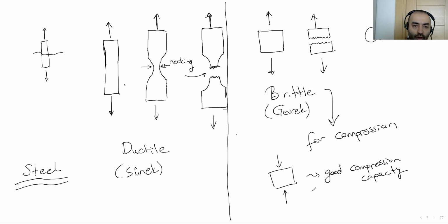It gets deformation, and we understand that, yes, it's gonna fail soon. Be careful. But brittle materials fracture suddenly. It doesn't give an alert. We don't know when it breaks. So that's why we don't use this material for tension.